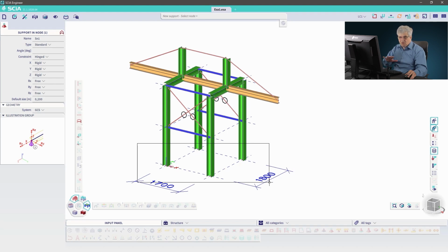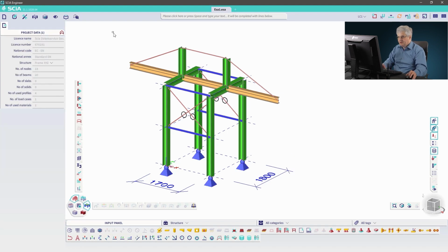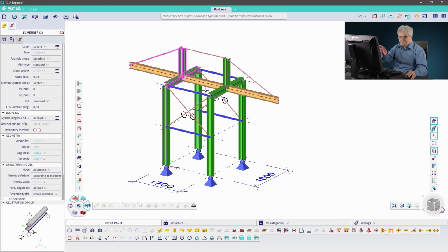This is standard in all CAD software. If you go from left to right, then everything is selected which is completely in this rectangle. If you go from right to left, you see a dashed line. That means everything will be selected which is completely inside and which crosses this line. So for this input it's not so visible, but if we want to select, for example, with this window, then only a part of the members will be selected, only members which are completely in this window.